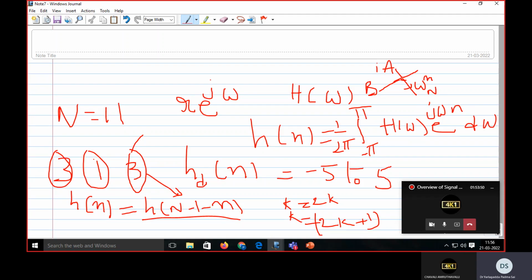Okay, so this is your butterfly. Actually, Ramesh Babu has put the arrow here. Many times I gave feedback, but they didn't correct it. Now this is the junction point. For the upper branch, it is a plus b only; you need not multiply for up. For the lower branch, after subtracting a minus b, you have to multiply with your twiddle factor omega n. According to our control system convention, the upper one should also be multiplied, but we are not multiplying. Because of that, the arrow should be here and this twiddle factor should be mentioned here.